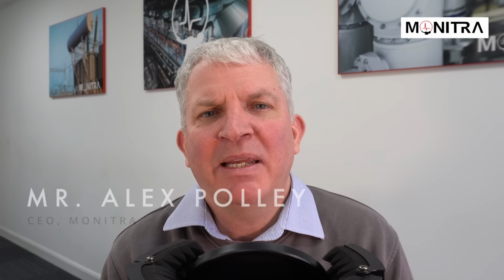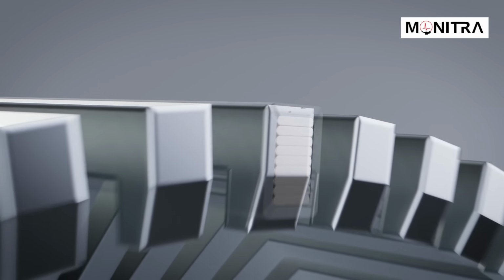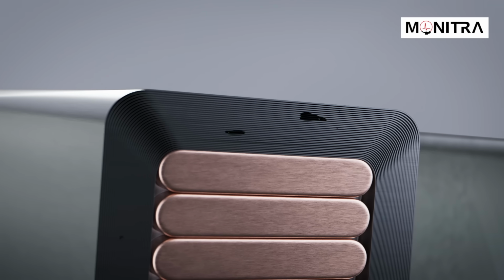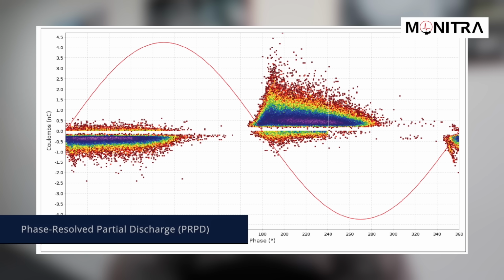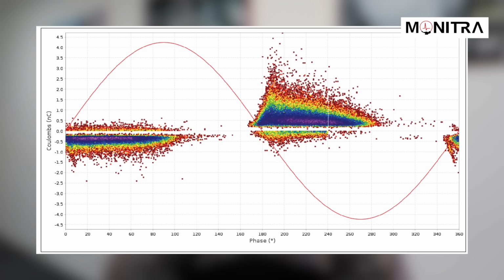Now, some of the common causes of internal PD include manufacturing defects, aging of the insulation, or improper process followed during the manufacturing process. Internal PD occurs deep in the insulation system, where unseen it can cause severe damage. In rotating machines, internal PD is one of many common defects responsible for the failure of HV stator windings. PD sensors for these assets include coupling capacitors or HFCTs. The signals derived from these sensors generate what we call a PRPD pattern, and the interpretation of this pattern confirms internal discharges and differentiates them from other PD sources such as surface tracking.